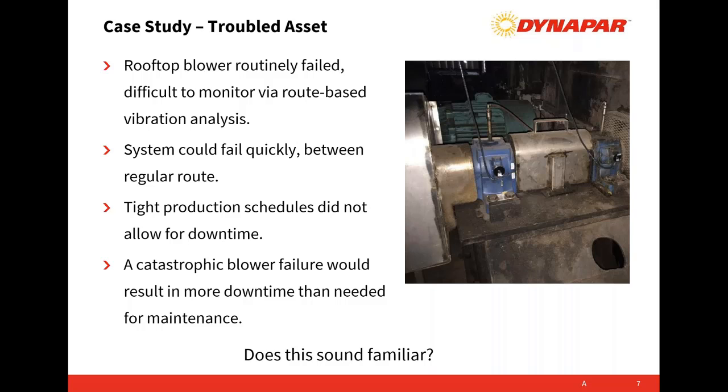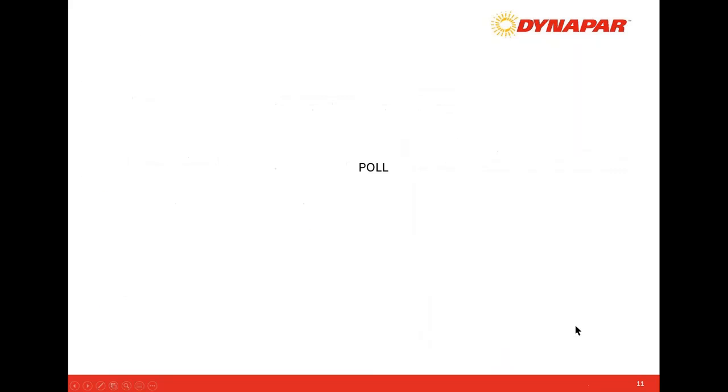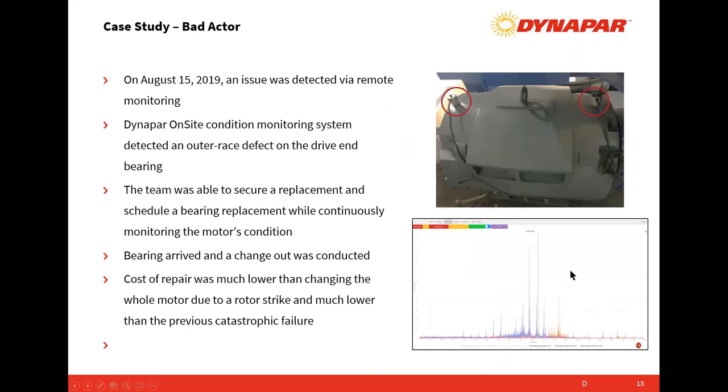I'm talking about pillow block bearings, mounted with a stud tangentially, and I know the XYZ axis. So now I can really begin to do the data interpretation. For a temporary or quick install, we could use the magnetic mounts. And again, those are for getting up and running quickly.